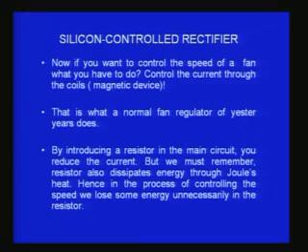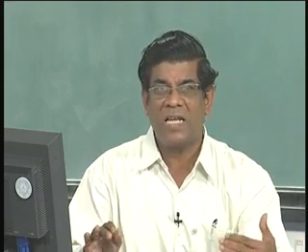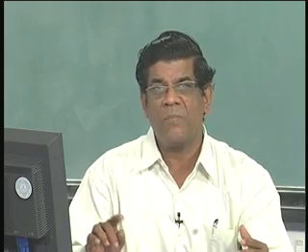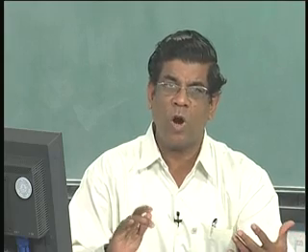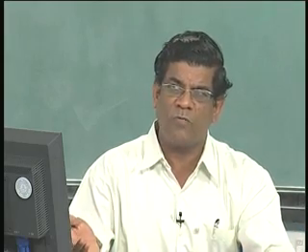rectifier. You would find the silicon controlled rectifier can act like a switch to switch on the power delivered to the load, or the fan in this case, at any instant you want, and thereby it can control the energy sent to that. To control this silicon controlled rectifier, we have the gate. I have already shown you the gate terminal, which is the control element, and you will still have to use a resistor to control the power delivered to the load, but this resistor now will come in the gate circuit, not in the main circuit in series with the anode and the cathode, but in the gate circuit between the gate and the cathode, and therefore the currents involved in the gate circuit are very small, usually of the order of milliamperes.